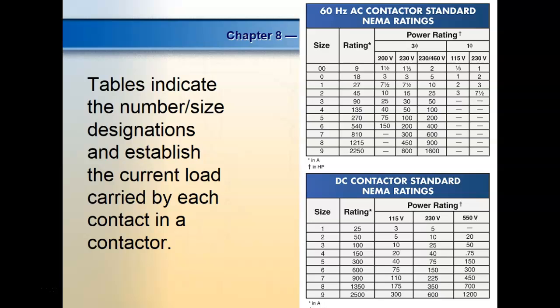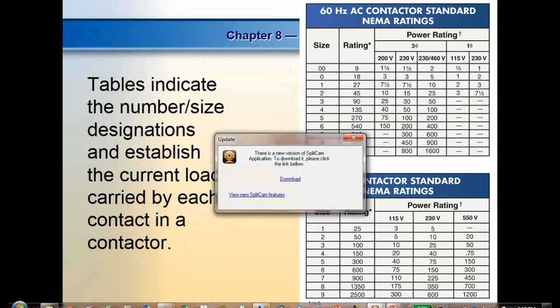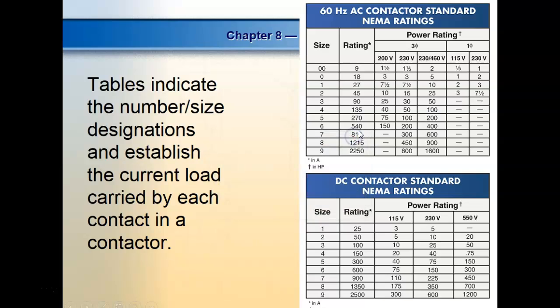Yeah, that is 00. I'm sorry. So ours is rated at one third horsepower. Thank you. I didn't even see that. So our motor is a 1/3 horsepower. We're running ours on 208. So we're basically not even taxing that thing, and we're running our motor unloaded. So that means it's not developing this horsepower at all, right? You understand? So are we okay?